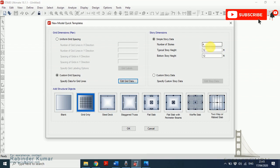For story data in ETABS, you have to provide the story data from the foundation level. For example, from foundation to plinth level we have a certain value, from plinth to first floor level, and from the first to roof level. So it will be a 3-story building.